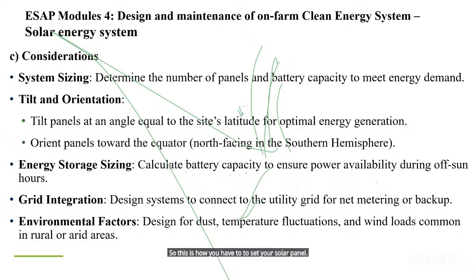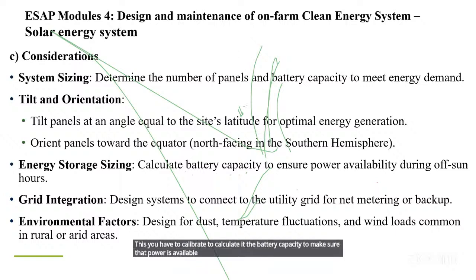So now, energy storage. It's about batteries that I was saying. You have to calculate the battery capacity to make sure that power is available during off-sun hours and during 2 days, 3 days, depending on your application, of cloudy days or of rain.